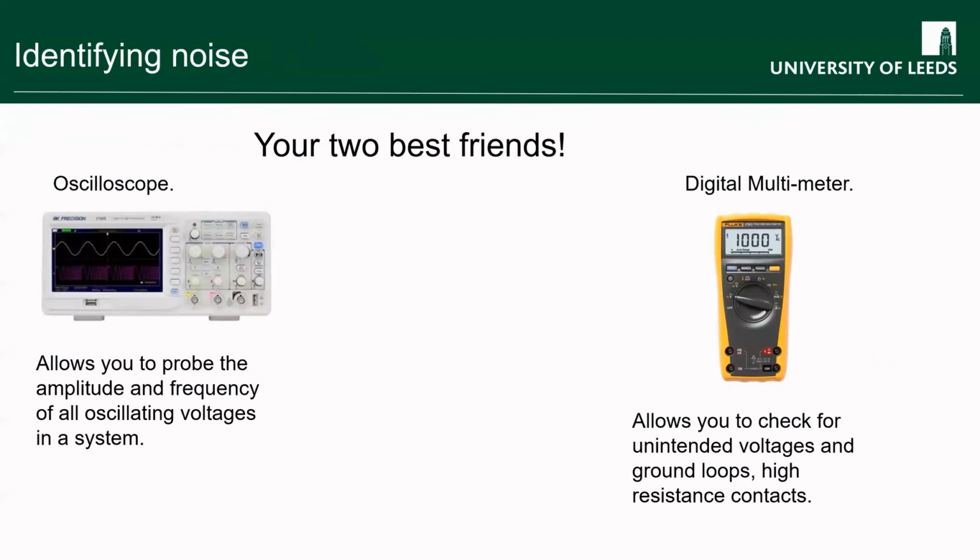So your friends for doing all of these sorts of tests and measurements, well, two things principally, obviously the oscilloscope, particularly if it's one that can do a Fourier transform of the signals. You can look at the frequencies, because there's often really useful information if you look at the different frequencies in the signal. You can decide on the basis of that what the likely source is. So for example, at one stage we were doing a measurement in the lab, and we saw things were a bit noisy, and when we looked at the Fourier transform of it, we realized that it was coming up every 5 hertz. And then we read through the manuals of all our equipment and realized that our temperature sensor was reversing the bias every 5 hertz.